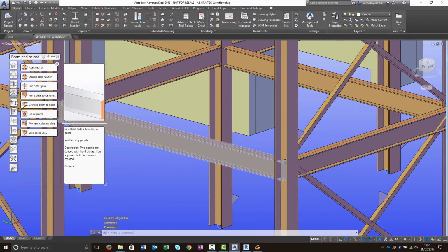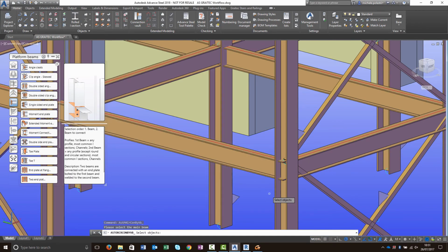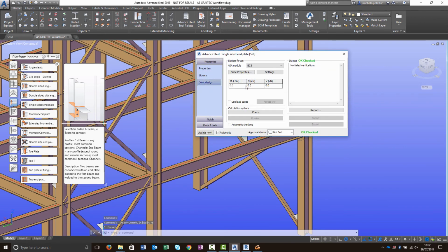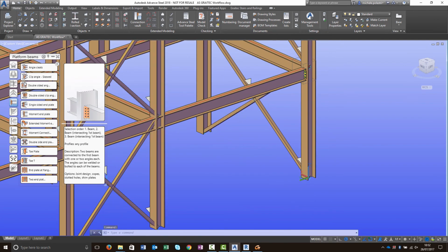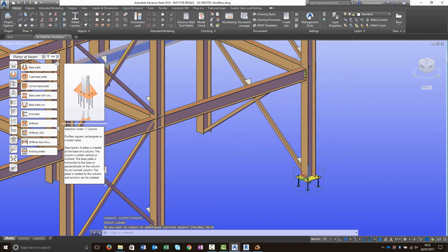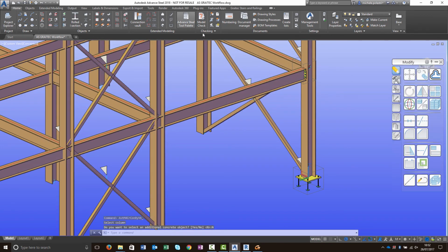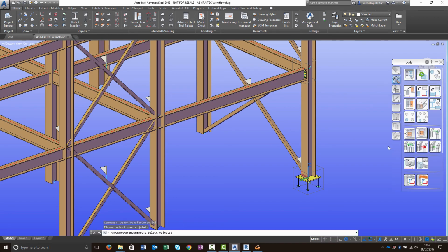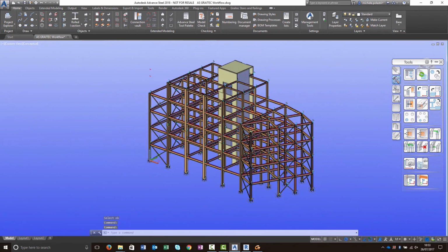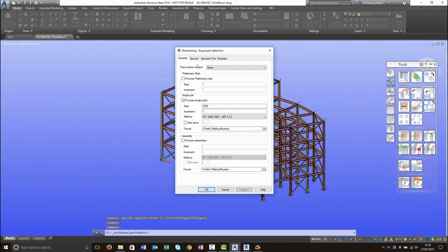We create as well a column base connection. Advanced Steel Connection Vault creates automatically the connection with the parameters indicated in the green book. Finally, we create the base plates and we copy them in all the columns. Now our model has also the connections inserted.